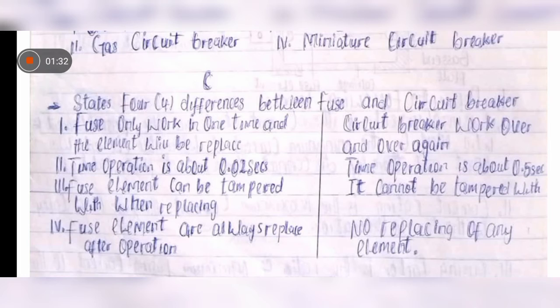Like I said, in my place of work, the place was making use of circuit breakers in the DB, you understand? So the socket that was connected to one of the circuit breakers in the DB, someone plugged his charger there, and the charger was somehow faulty to the extent that it caused a spark in the socket. The charger spoiled, and the socket also stopped bringing light at the indicator. So a student asked if the socket was damaged also. The reply was no, that the circuit breaker in the DB will rather trip off than the socket spoil. And truly, when we got to the DB and turned the circuit breaker back to its normal position, the socket started working. It shows how useful the circuit breaker is.